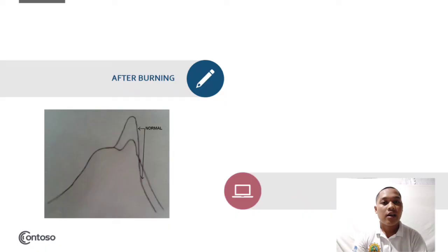After burning, indication and effects. A rise in the expansion line is recorded in the later part of the piston stroke. Since burning of fuel continues, exhaust gas temperature and pressure increase, causing black smoke at the engine's exhaust. Unburned carbon deposits foul the exhaust system, cause damage to the exhaust valve and seat, turbocharger surge, and there are chances of uptake fires in the exhaust gas economizer.